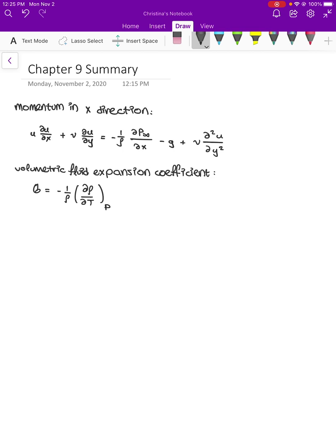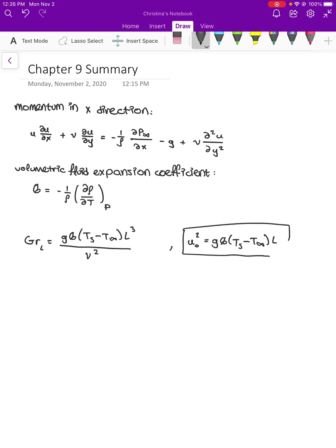The rest of this chapter defines Nusselt numbers for various geometries. Before covering those, I need to mention the Grashof number, which is another dimensionless group. The Grashof number is analogous to the Reynolds number squared when we take the following velocity. For this reason, the Grashof number plays the same role in free convection as the Reynolds number in forced convection.